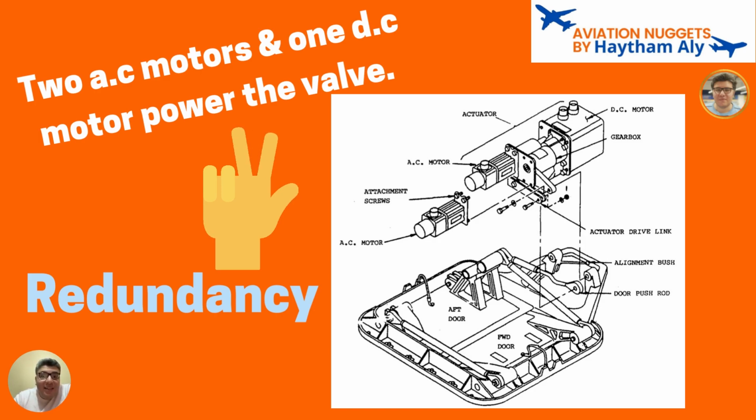So why do we have AC and DC? We need different aircraft electrical power sources, and also it is regarding the speed. If we need to operate the outflow valve at a fast speed or a slow speed, we may have an AC motor and a DC motor. So in total, we have at least three motors powering the outflow valve.